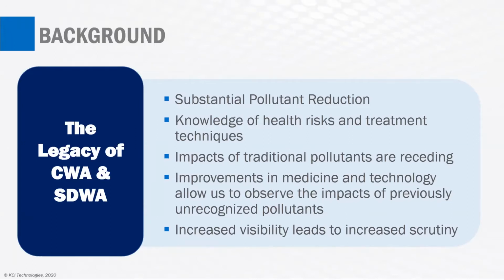The successful compliance with these acts resulted in the development of a wealth of technologies and processes that can provide superior removal efficiency of conventional contaminants, such as BOD, TSS, nitrogen, phosphorus, to name a few. It also can produce high quality water suitable for reuse, and consequently, it minimizes or eliminates the adverse impact of these conventional contaminants on the environment.